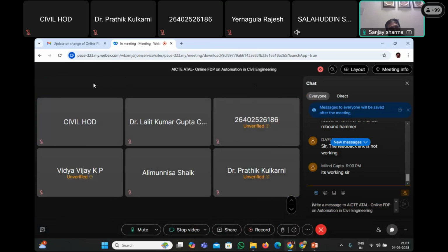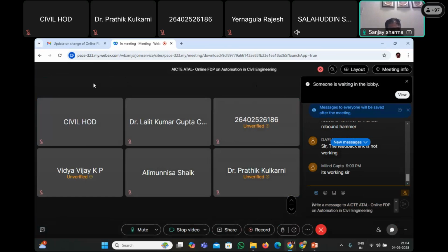But you can repair. We suggested some repair in the Kalka and Shimla region, where very old structures, piers, and so on were there. By visual inspection we found, say, joints were broken down, and we suggested high pressure grouting with a high bond strength material. Through that, we asked them to strengthen the structure, so they carried it out and it worked.